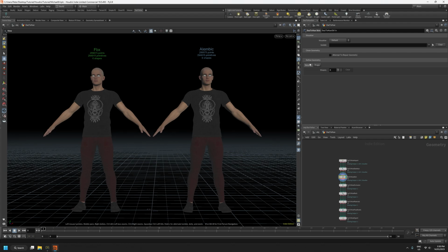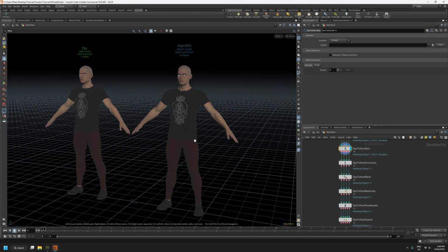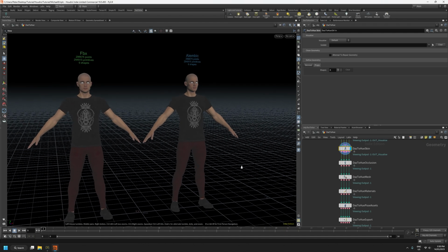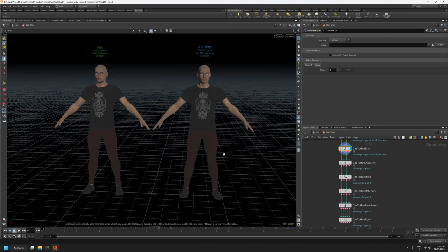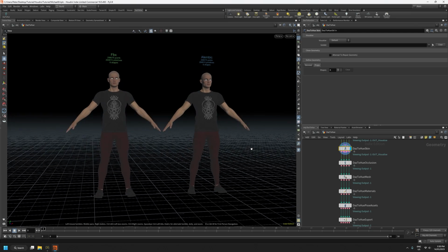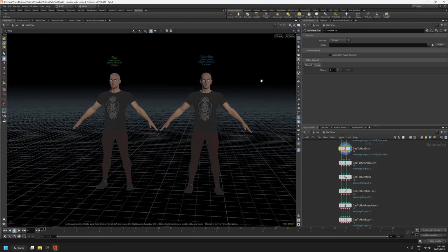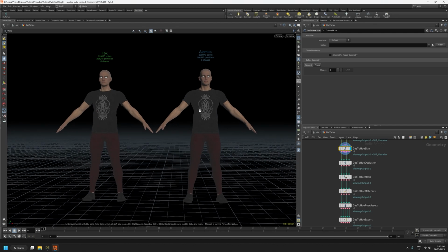Shapes are broken down into 2 different types. We have the skin shapes. Any skin shapes are included in joint corrective morph calculations, so they will have morph targets generated for them. And prop shapes are excluded from any joint corrective morph generation. They are treated as non-deforming geometry, typically weighted to a single bone. This particular character doesn't have any props, so we'll disregard that section for now. But we will define some skinned geometry shapes.